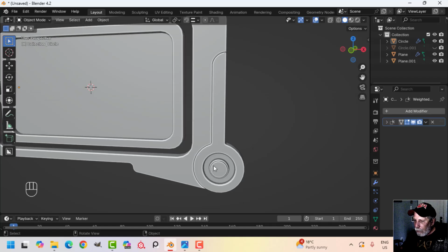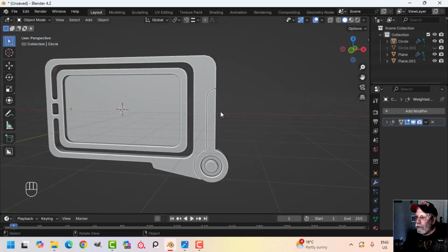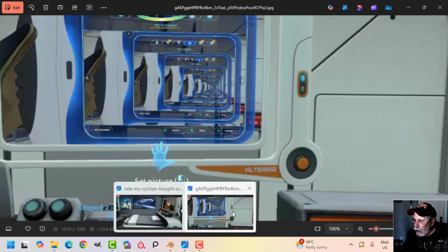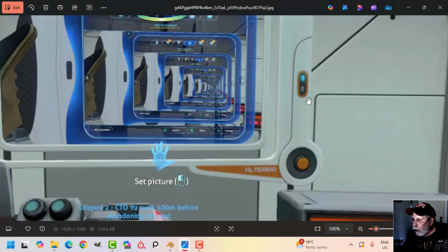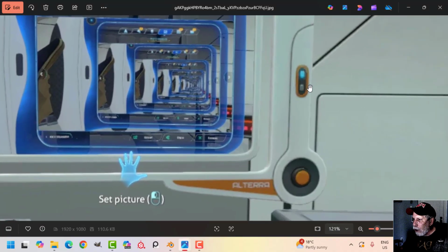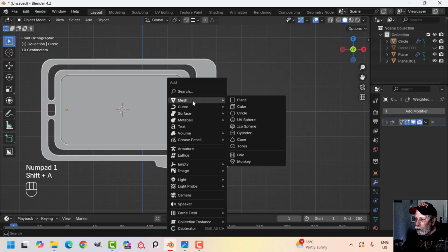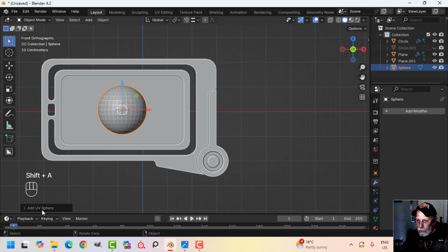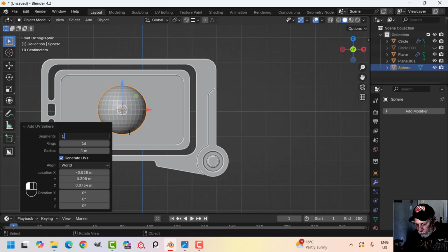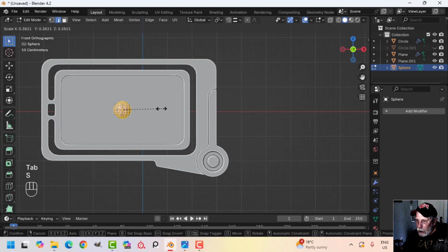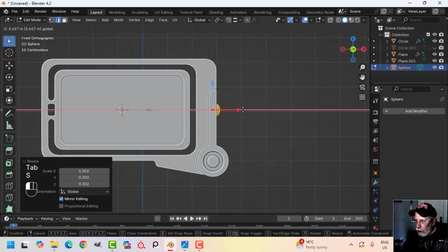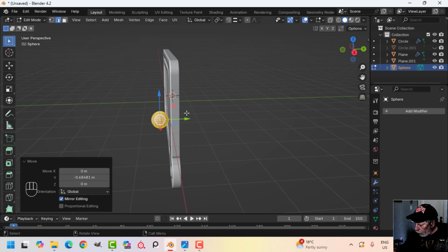All right, there's just a couple more things that we're going to do, and that is over here, there's this structure here. I'm going to do some of this in texture, and I'm going to do some in geometry. So I want to create these pill shapes here. So I'm going to bring in a UV sphere. I'll bring it down to 16 here, and scale it down and bring it over here. I think this is the way I'm going to want to do this.